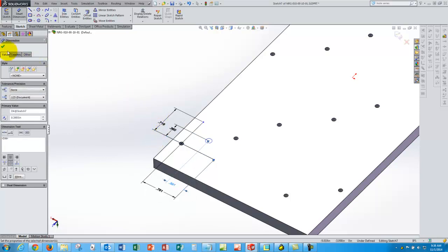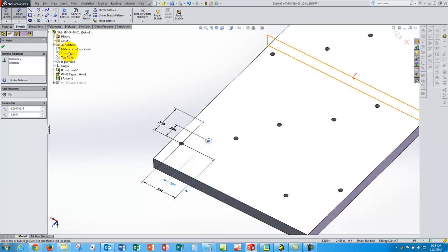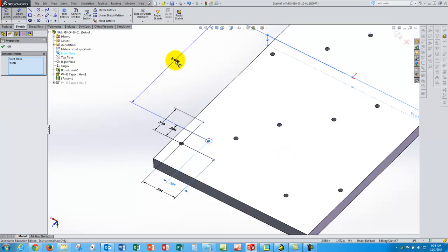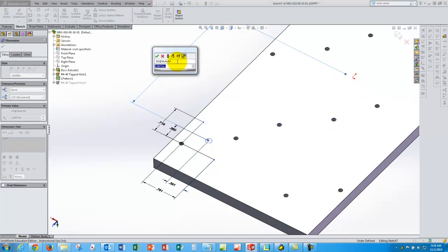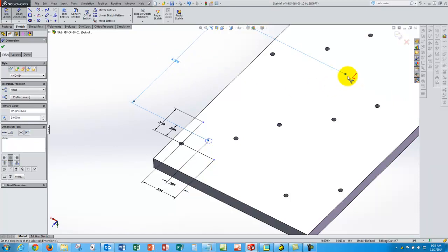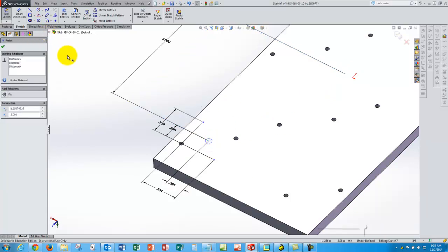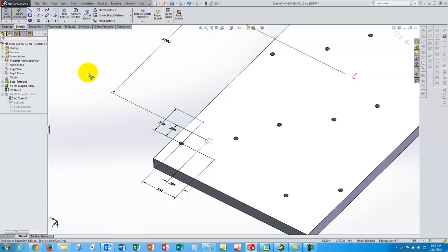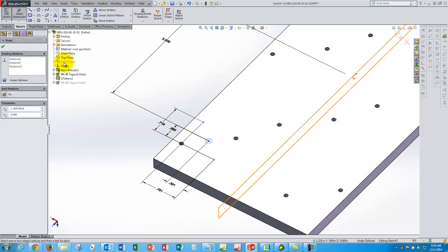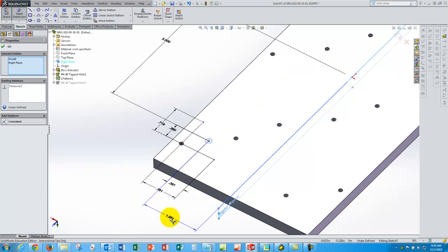So now that circle is in the middle of the hole pattern, and now I'm going to locate this construction circle, relative to the planes in the part, to locate them where they need to be with the resistors. So this will move slightly since I put those other dimensions in there. That should be 3. And this other dimension here needs to be to the right plane. Lost my dimension button. So there to my right plane needs to be 1 1/4.